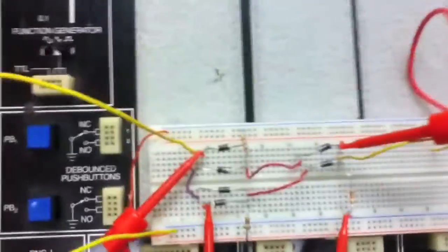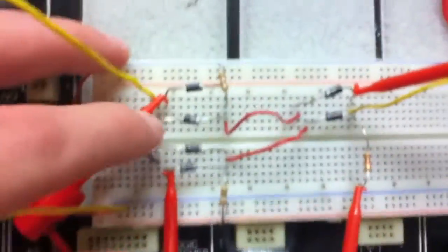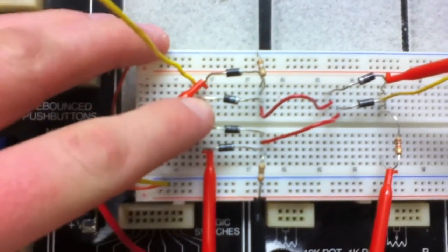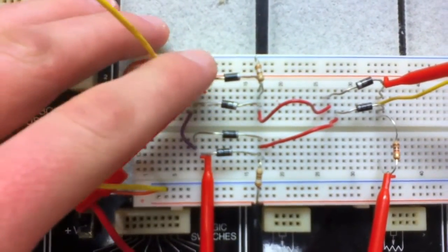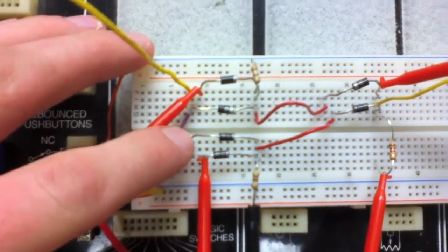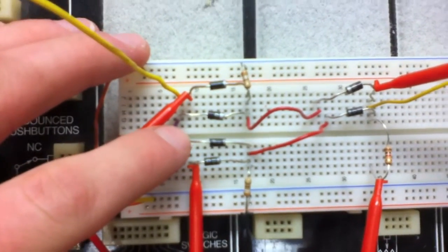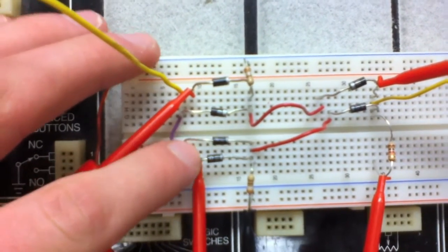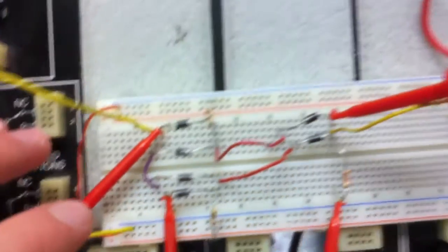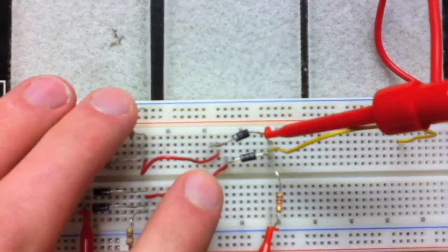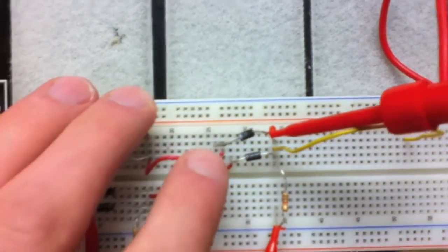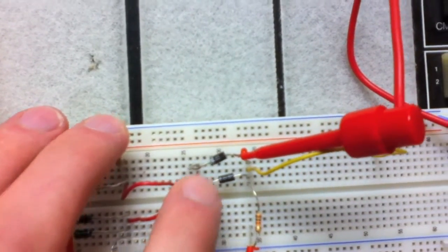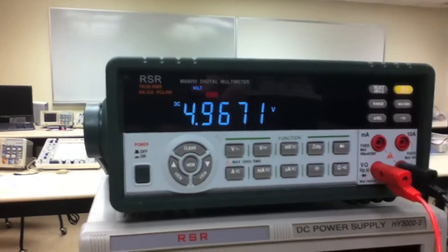Yeah, so here's our circuit. We have the two diodes here at the top, which is the first maximum circuit with a 3 volt and a 5 volt, and then the next maximum gate is this 5 volt and 7 volt. The outputs are brought over to this minimum gate, which has an output of roughly 5 volts, as you can see on our multimeter.